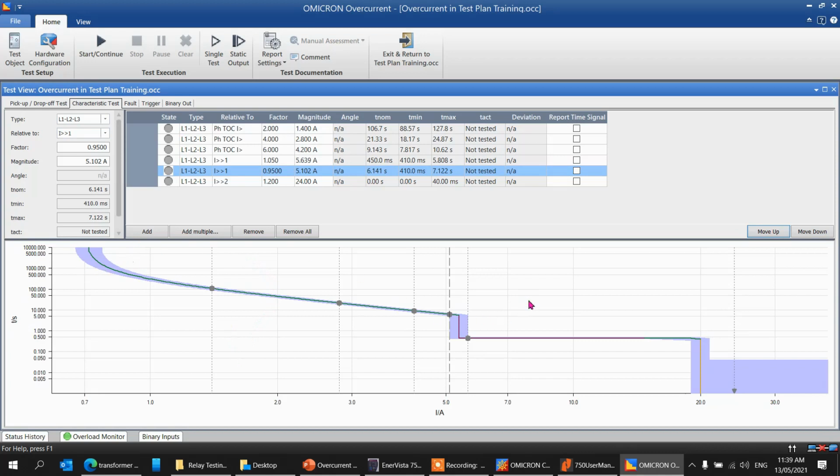So yeah, I think that's the test plan that we have. And in this setup as well, you don't need to disable, because I saw some relay testers disable. Let's say they want to disable this one just to do 2, 4, 6. Isolate. No need to do that. You don't need to disable, as you're defeating the very purpose of the curve.